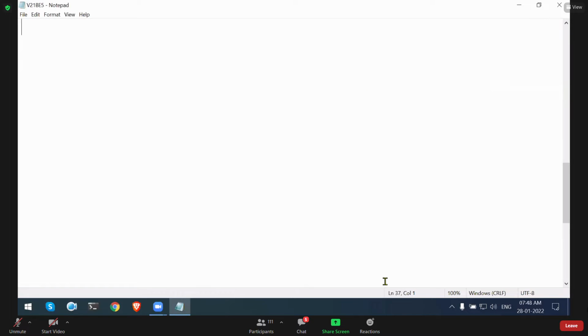For example, if you are using an Arduino board, there is no need to press the reset button. When you dump the hex file, it will be dumped automatically. But on most microcontroller boards, you have to press the reset button.